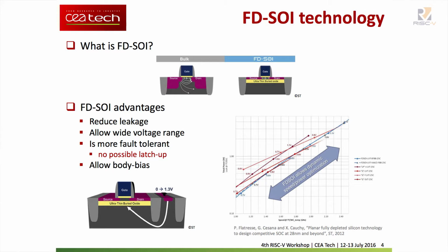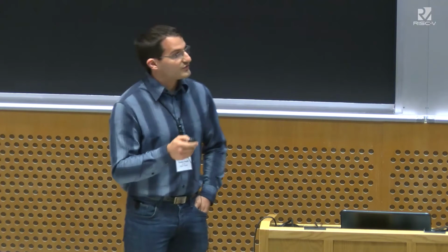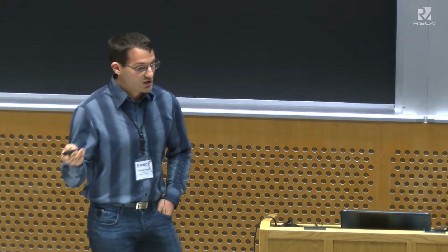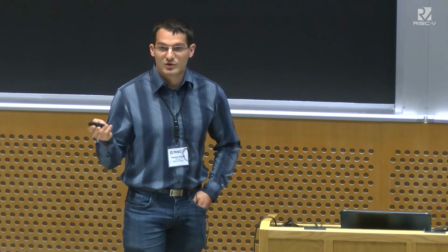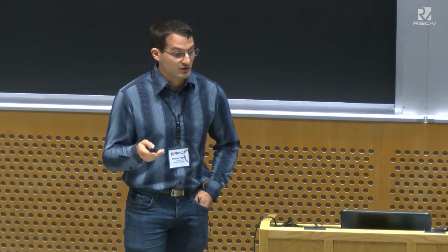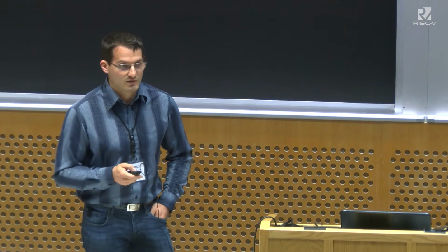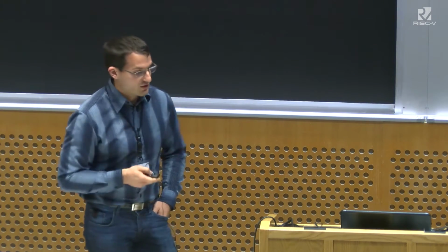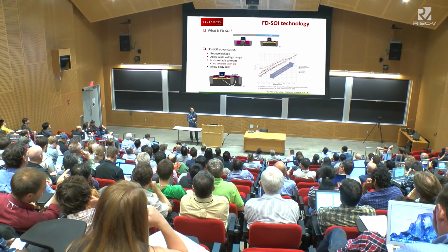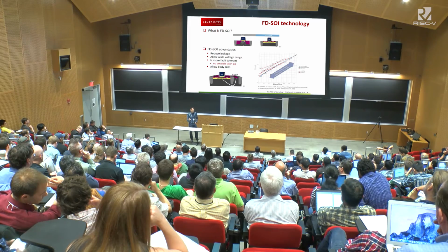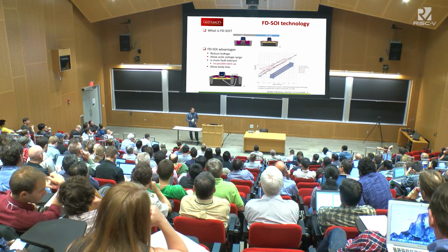In FD-SOI technology, which means fully depleted silicon over insulator, the size of the channel is slightly reduced, thus reducing the leakage, and removing some parasitic bipolar transistors, which can cause latch-up. It also allows body bias technology, which I illustrate here in the left corner. That means that under the transistor, you can apply a voltage that modifies the way the transistor behaves.